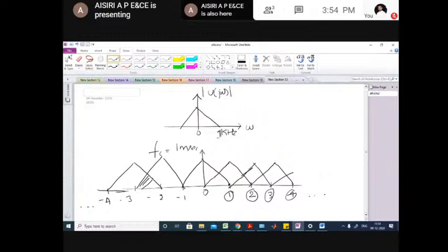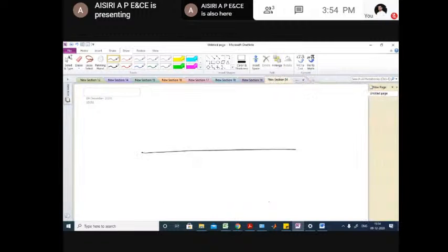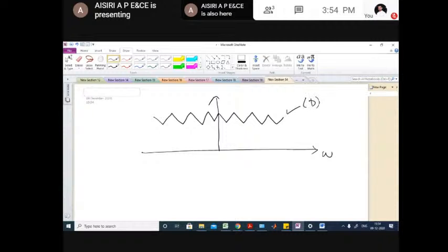This is resulting in the aliasing condition. So you can see here, aliasing is happening over here. There is an overlapping of the replicas, which results in no faithful reconstruction of the original signal. So what is the frequency spectrum of the signal now? So that will look like, if this is omega, this frequency spectrum of my sampled signal will look like this. So that is option D is correct.